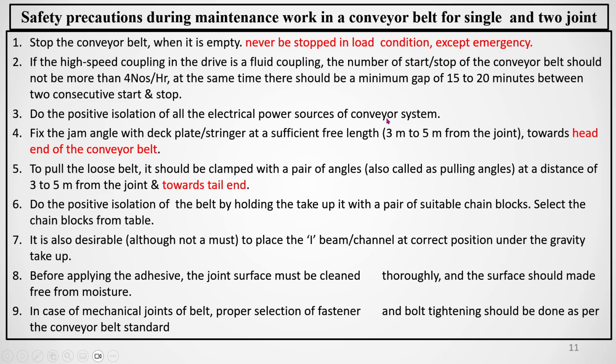And then the minimum gap between two starts should be 15 to 20 minutes between two consecutive starts and stops. So you have to provide that 15 to 20 minute stop gap. Do not start immediately. When you stop, you have to start again only after 15 to 20 minutes.